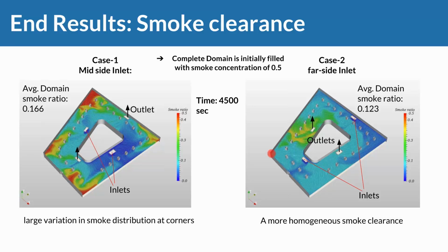And here we can see that with the same energy being used, just by doing a more intelligent placement, we can see that on the right we brought the smoke concentration significantly more down than on the left. So we end up with 12% on the right, and we end up with 17% of smoke concentration on the left. And that's just, again, you bring in your CAD model, you upload it to SimScale, you set up the physics, and you can do such a prediction based on CAD data.